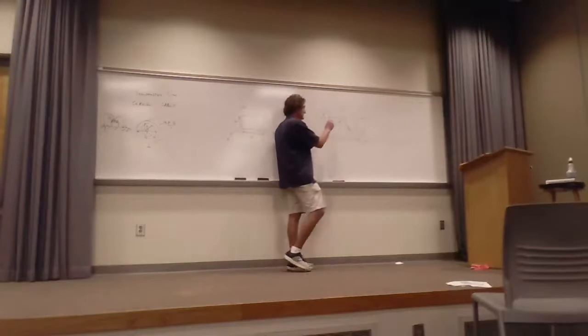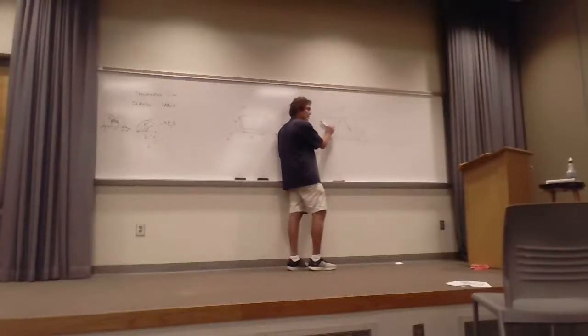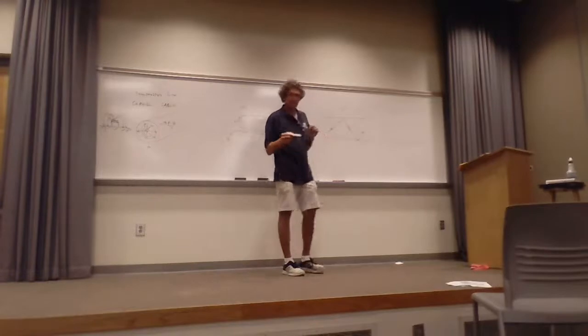Now, if the electric field is in this direction, it could still have a component in the direction of propagation, right? Depending on how it's bouncing, but it could have a component along that direction. But the component in the direction of propagation would have to go to 0 here and here. Does that make sense, Steve?